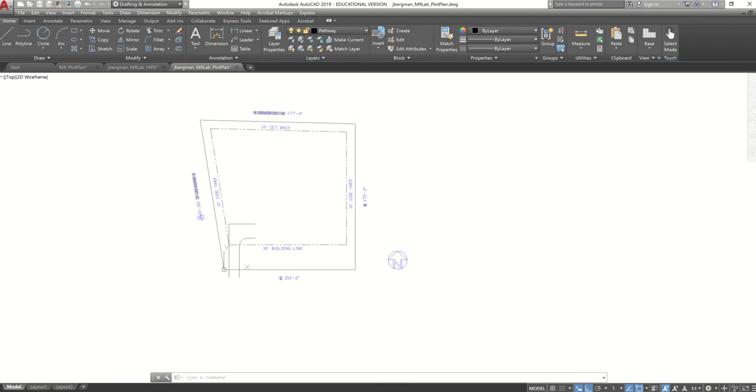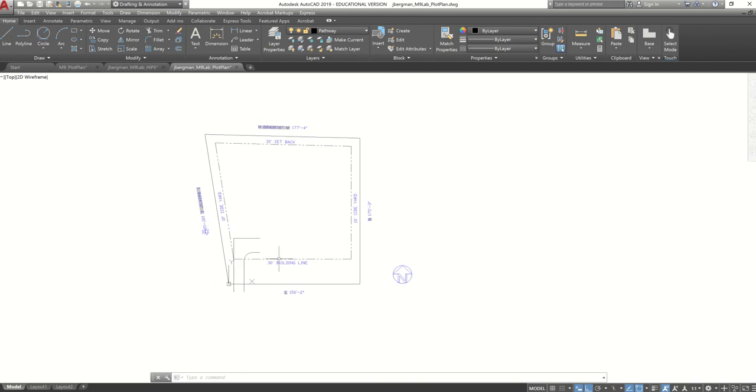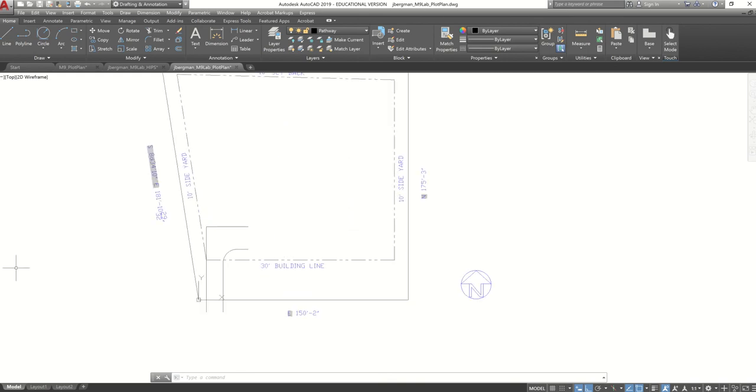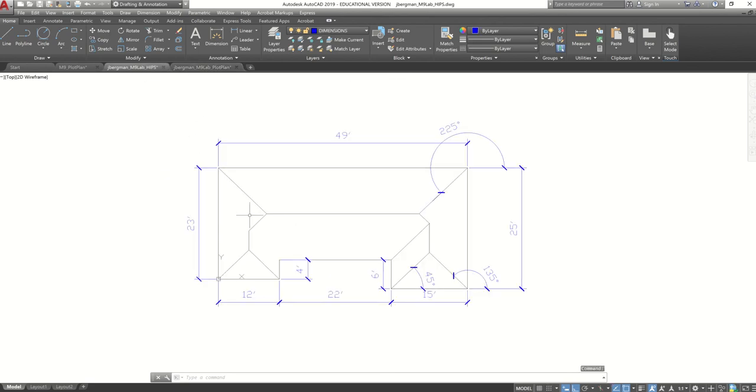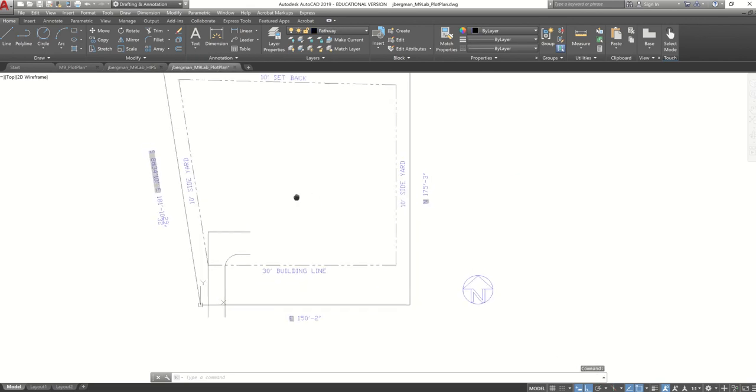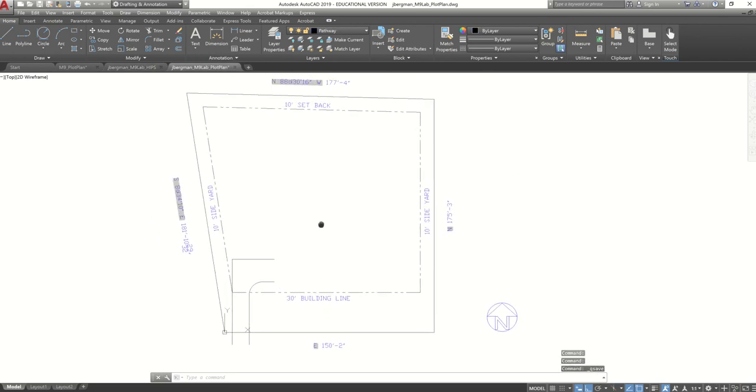and you can go in and dimension it if you'd like. You don't need to dimension it. And then we are going to add our external reference of our hips. So I'm going to go into hips and hit save really quick. So Control S, and then go back here, and I'm going to do Control S to save. And then I will just type in xref, enter.